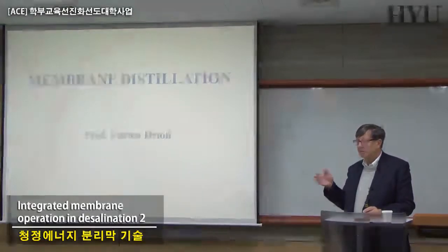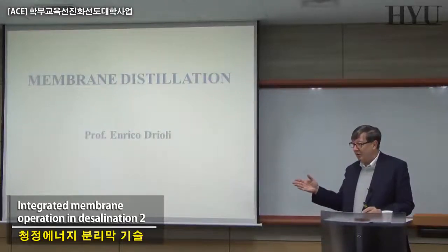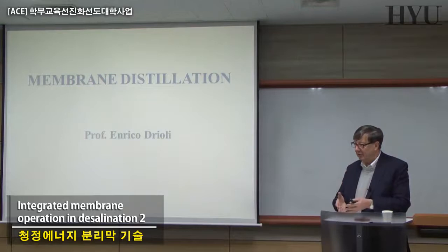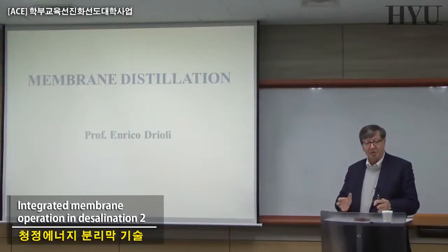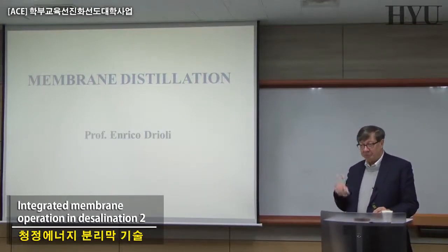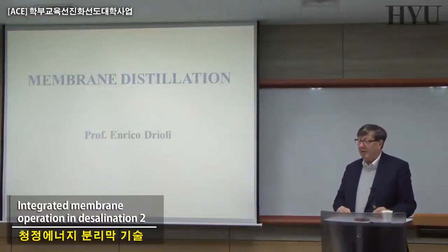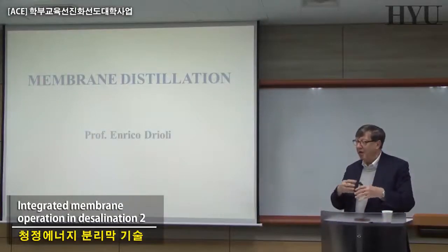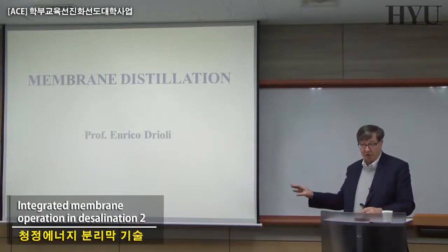Distillation, crystallization, condensation, emulsification are already basic unit operation in process engineering. Not based, however, on the use of membranes at all. Totally different system. Today, slowly, in the logic of process intensification more and more, process engineering is readapting some basic unit operation as the one I was mentioning: distillation, crystallization, emulsification, condensation, drying, dehumidification, etc., using membranes.